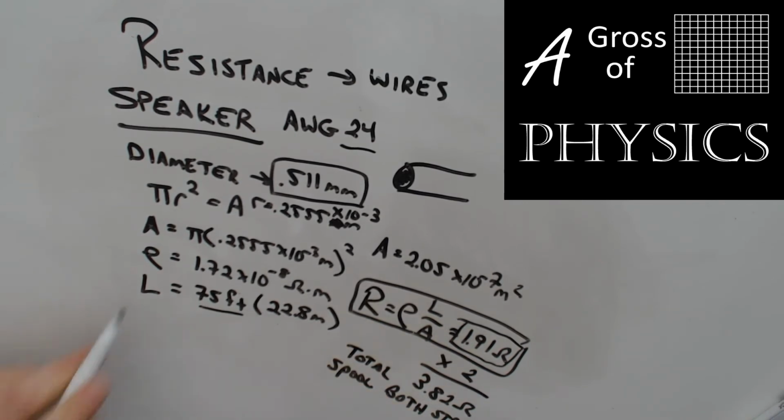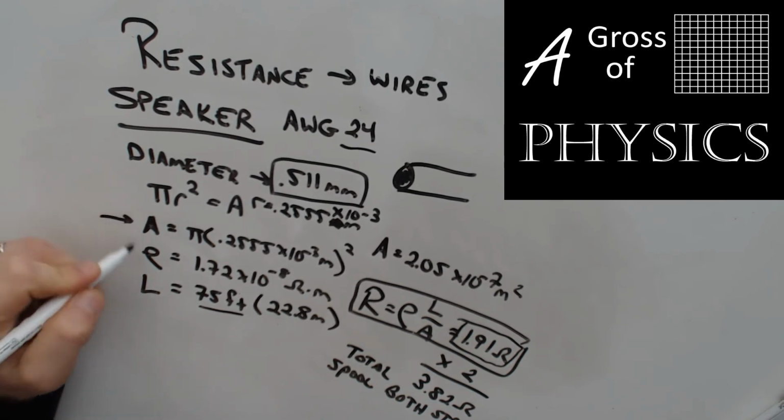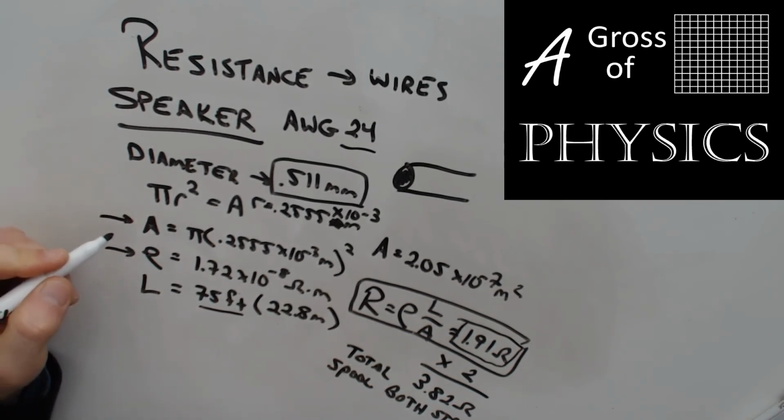So you need to look up a few things. We had to convert a number or two, watch out for diameter, and finally resistivity is going to be listed in a chart. And our chart has 6 common values, and if those aren't ones that you're looking for, you'll have to look it up on a different chart.